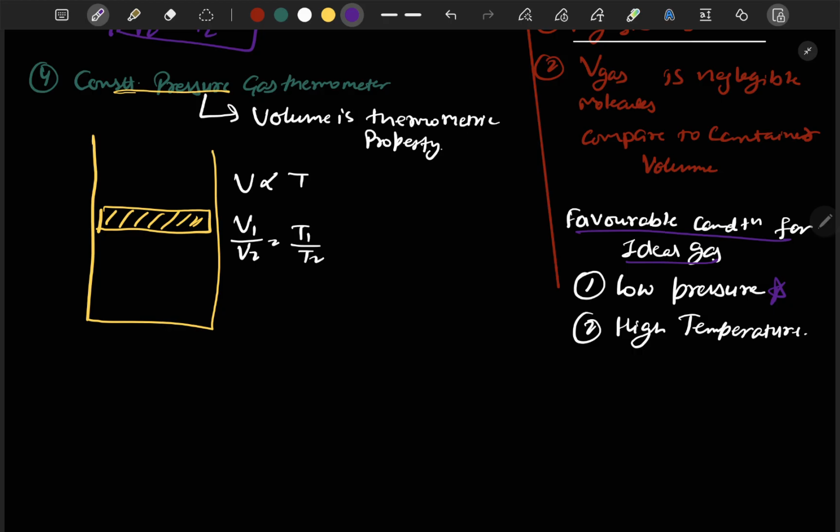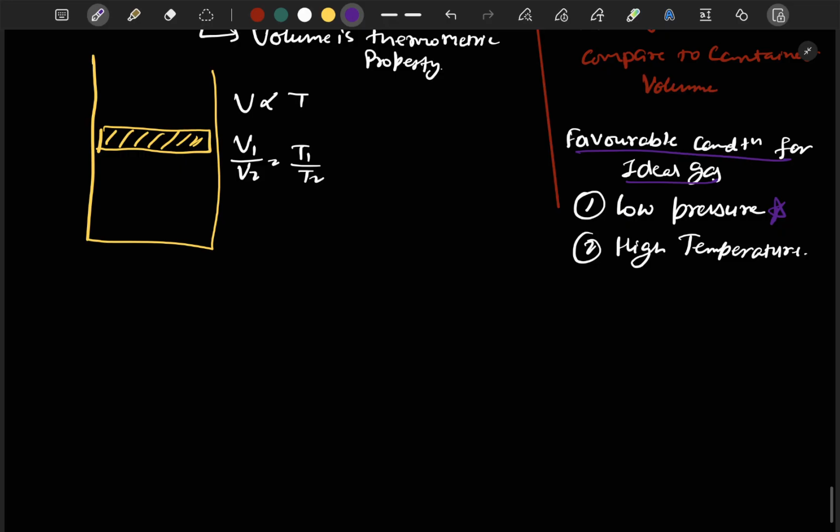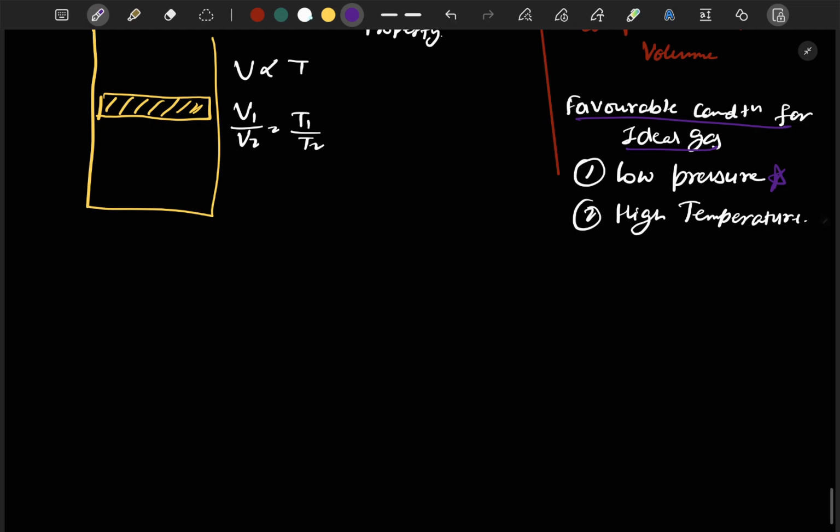Okay, so all substances naturally existing as gas, like oxygen, nitrogen, helium, argon, should be considered ideal gas in all the further questions which we will be doing. One point you should remember is that steam is not an ideal gas. Steam cannot be considered an ideal gas unless it is a helpless situation, with nothing given in the question. If the question says we can consider steam as an ideal gas, then only we will consider it. So, what is the equation of an ideal gas?